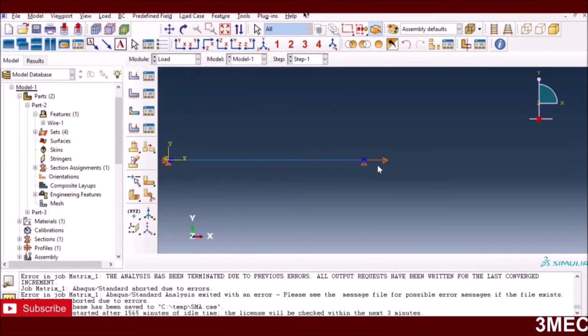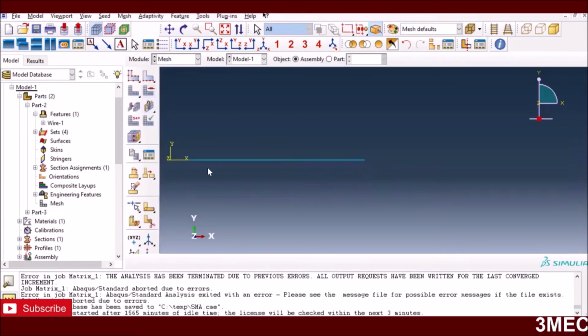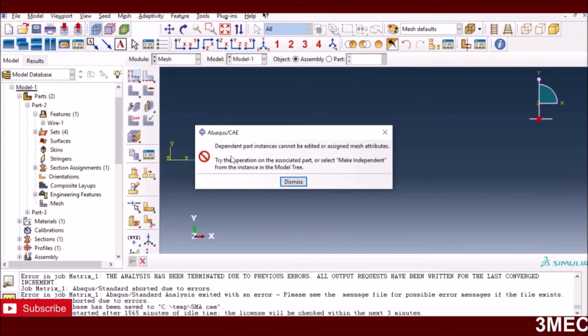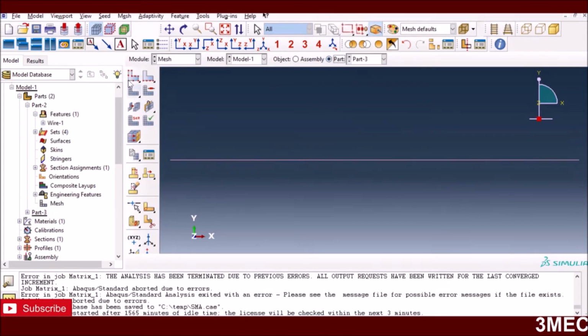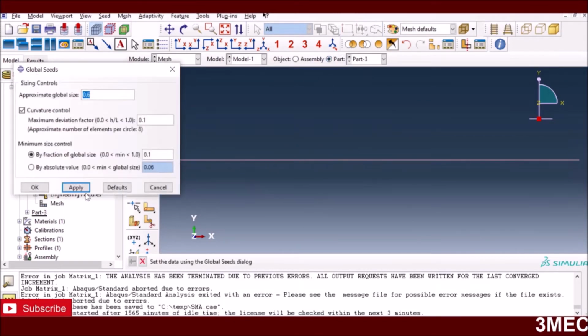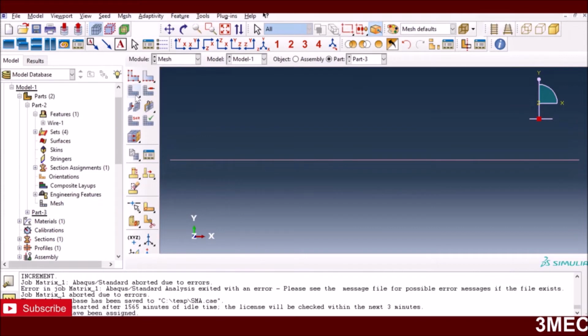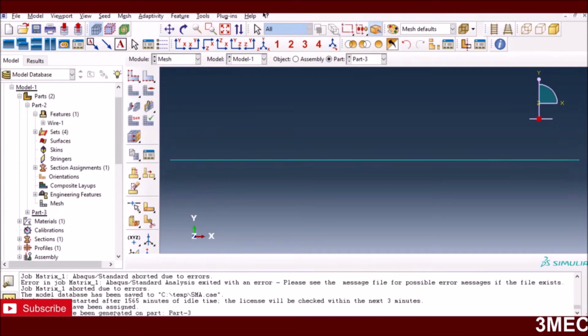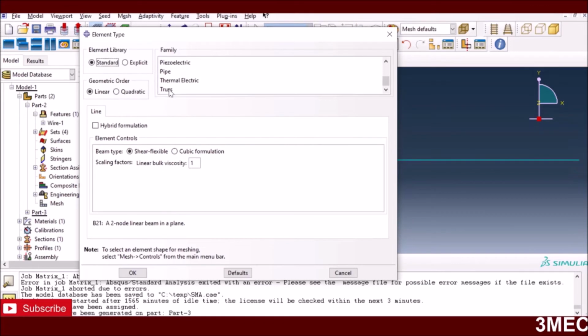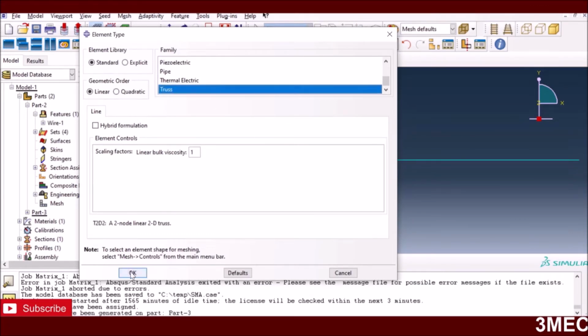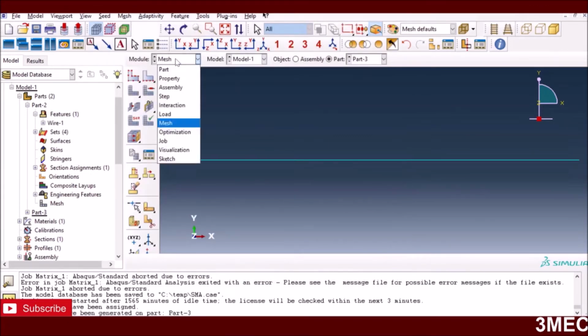So this is what I have done here. It goes like this and then comes back to 0 to capture that cyclic effect. Meshing, I only use 1 element here, so I just say the total length is 1. So I will have only one element here. Okay, and then I mesh. So you can see I have only one truss element, and if I show you my truss element, it is truss, and it should be okay.